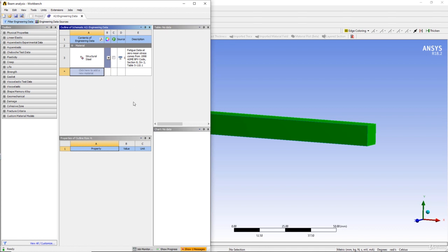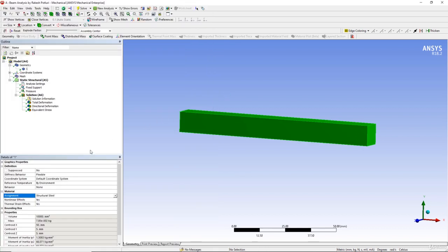Now using this Ansys Engineering Data Manager, you can add new materials, and once you add new materials, those materials will be available for assignment here in this particular version of the Ansys software. So this is how you can control the materials that are being applied to any geometry inside the older versions of the software. Now I will switch to the newer version of the Ansys software.